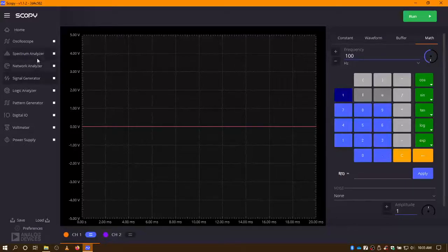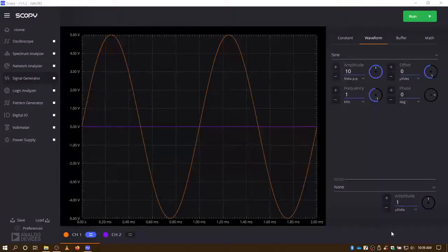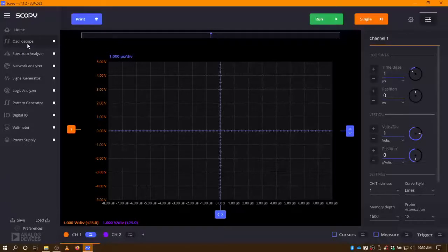So pretty much that's the simple portion. Next, we're going to go into how to deal with the oscilloscope. Okay, to look at the oscilloscope, we'll click on the oscilloscope feature. The oscilloscope itself is made up of 2 differential channels that can measure a signal that's plus or minus 25 volts. The key thing is it's a differential channel, and I'll get more into that later. The signals are measured by a 12-bit 100 megasample per second ADC with a bandwidth of 25 megahertz.